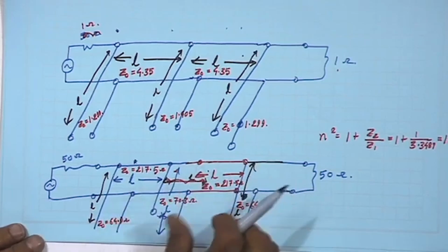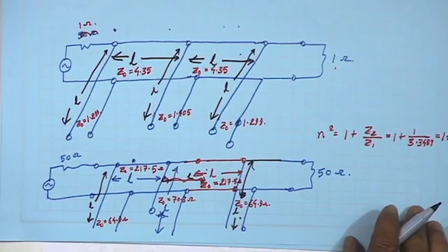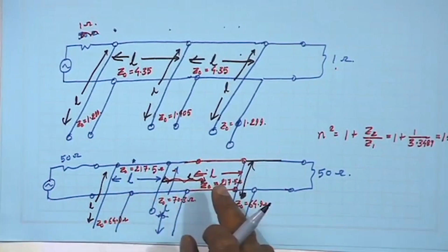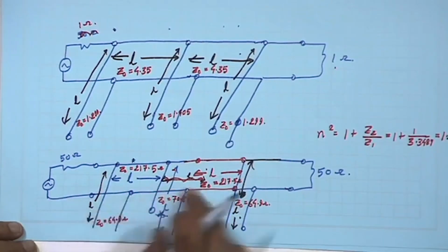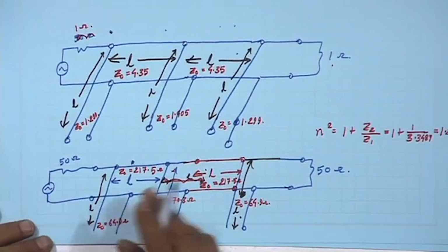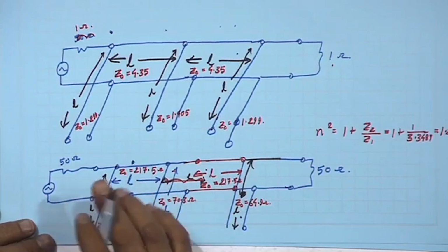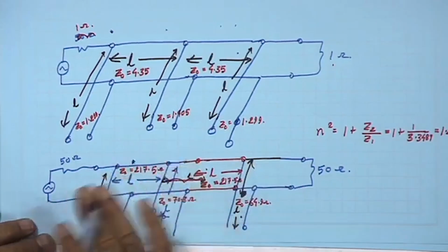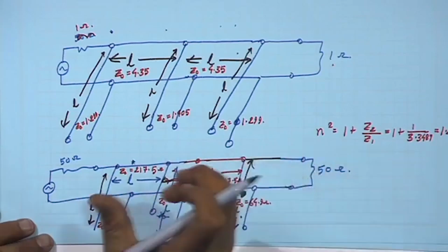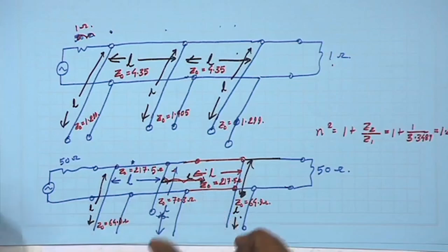I have separated them. Now, these unit cells are called redundant sections, they are matched, because their impedances on both sides are matched to 1. That is why they do not disturb the operation of the filter, but what they do is separate the 2 stub elements, so there is enough separation between them.